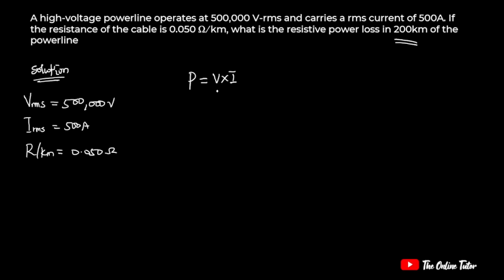Resistance still remains resistance, and depending on the component that you have, the resistance may change to impedance, which is the overall resistance if we have a capacitor or a resistor or an inductor inside, but that will be for another tutorial. So we have power equal to voltage times current. But we know from Ohm's law that voltage is equal to IR, which is current times resistance.